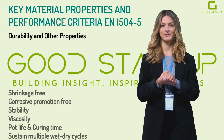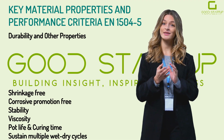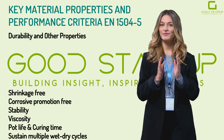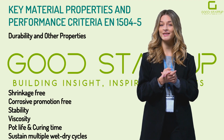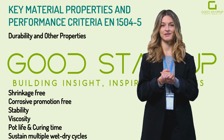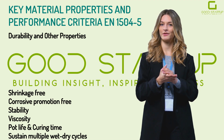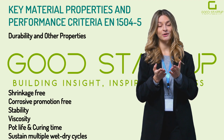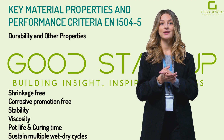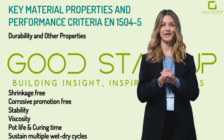Durability and other properties. The standard also covers durability aspects such as resistance to chemicals, thermal expansion behavior, and aging. Crack fillers should be non-shrinking, or slightly expanding for swelling types, non-corrosive to reinforcement, and stable over time. Viscosity, usually given in mPa·s, is an important parameter provided by manufacturers, as it indicates how easily the resin can flow into cracks of a given width. Pot life and curing time are specified for different temperatures to ensure the material can be injected before it starts to gel. For swelling materials, Category S, the expansion ratio and the ability to sustain multiple wet-dry cycles without performance loss are key parameters. Manufacturers will declare these values in accordance with the standard testing.